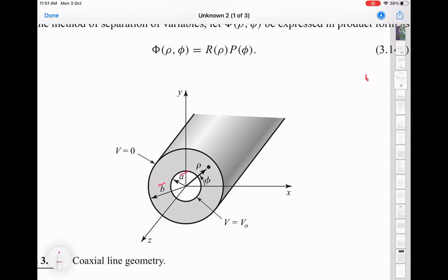So what's the relevant thickness? The skin depth. Right? As long as your metal is thicker than the skin depth, the field is not going to propagate in those regions. So then you're good. Talking about the surface resistance of the outside metal, I'll come to the inside part. This is just to explain which dimensions mentioned here are important for the purpose of a transmission line and why others are not relevant,